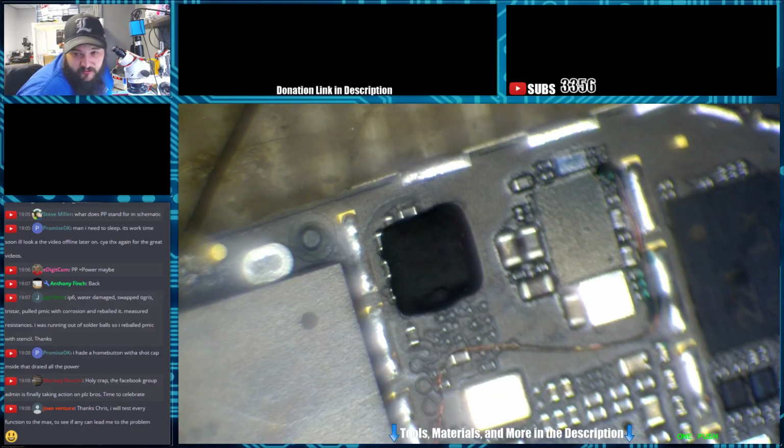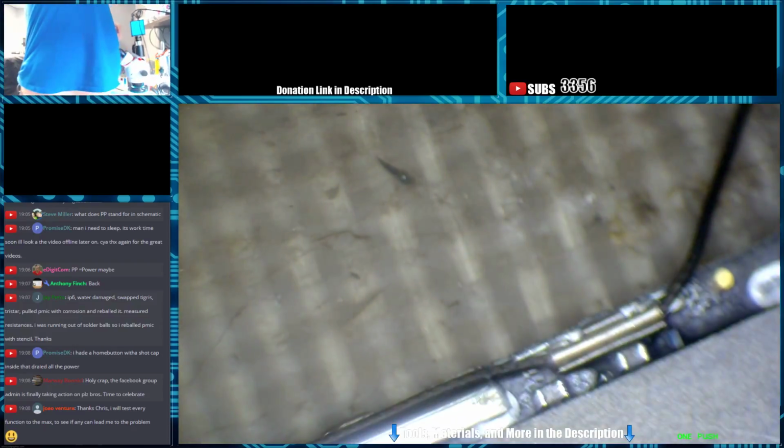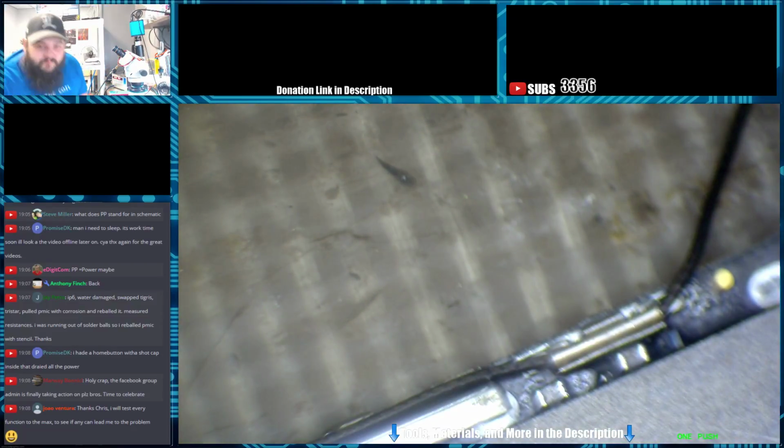Alright, so let's not put this off any further. Let's go ahead and put our resistors on. Let me grab a parts board. Alright, so I've got iPhone 6s for days. The iPhone 6s have 2.2K resistors on some of the I2C lines, so I'm going to go through and find those. And we're going to snag two of them.